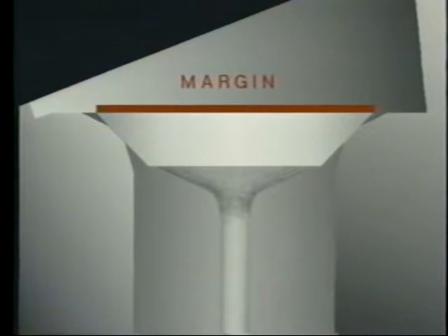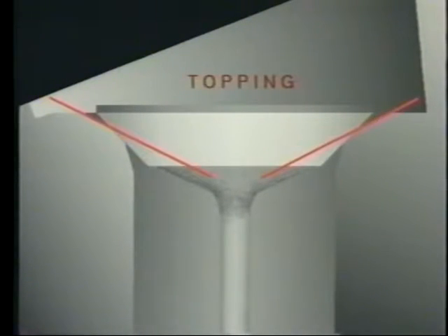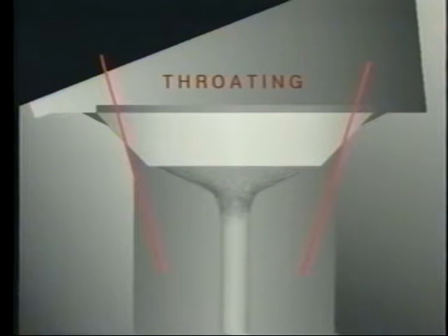Other valve measurements, such as valve margin and seat width, must also be considered when grinding or cutting valves and seats. When measuring and adjusting seat width and location, procedures such as topping or throating may be necessary. Be sure to review these procedures before taking the ASE engine repair test.